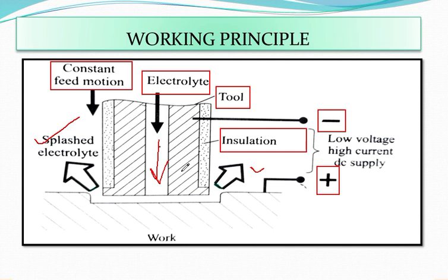Again I am repeating, have a very clear look at this particular point. The electrolyte is so chosen that the anode is dissolved. I mean to say anode means your workpiece is getting dissolved, but no deposition takes place on the cathode, I mean to say over the tool.